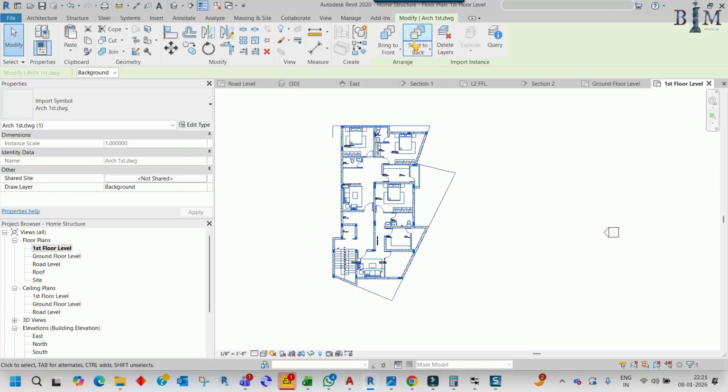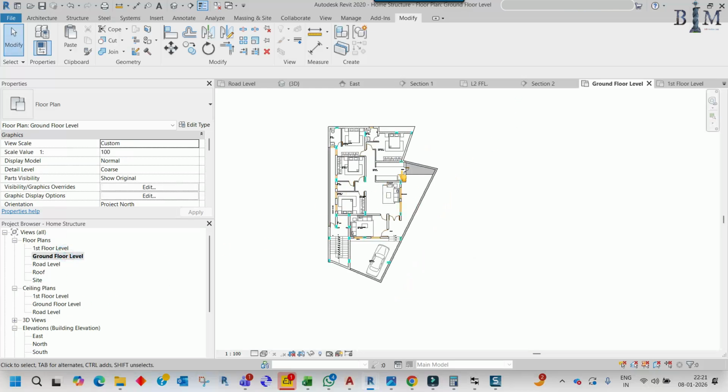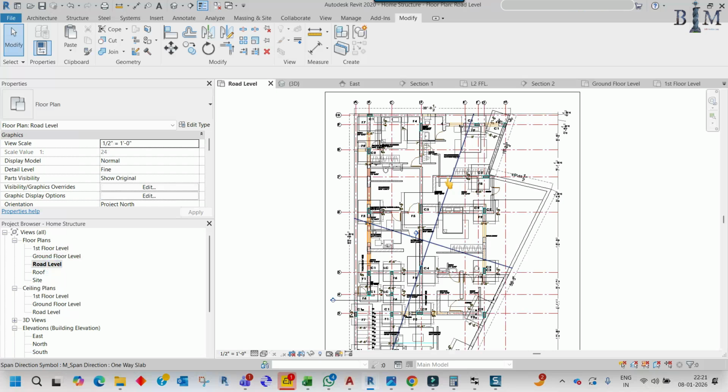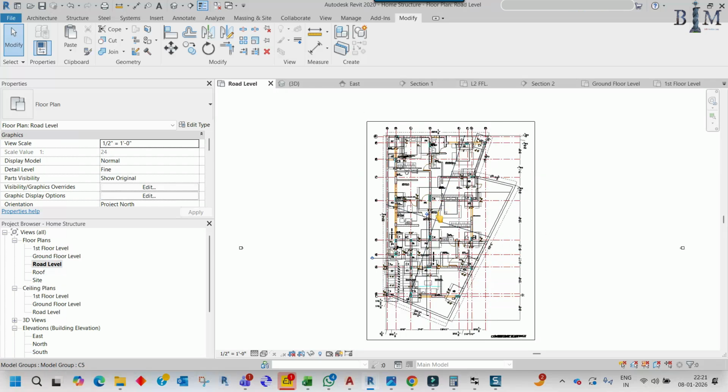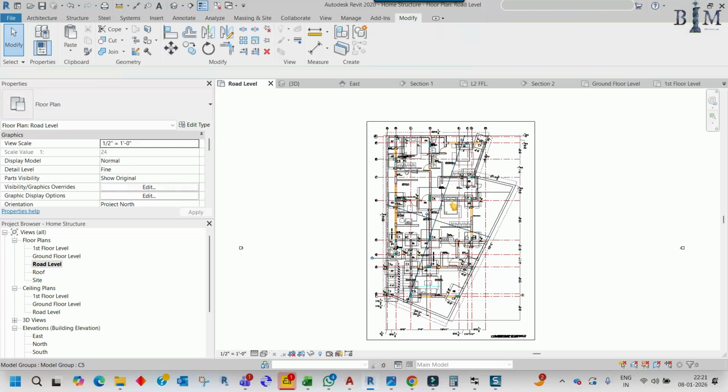So select this, and here pin the element. Close the pin and attach option, and now you cannot select anything in this drawing. There is no snap here, you can only select the Revit element. This is the only snap line, but no problem, leave it for now.